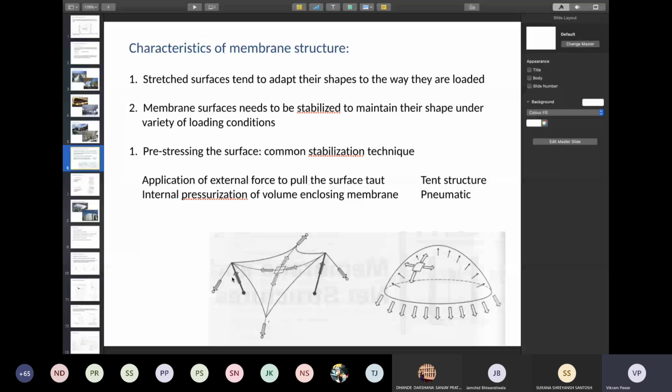Also, in this case, you have something called an anticlastic surface. One direction of the curvature is upwards, the other direction of curvature is downwards. With these two opposite kinds of curvatures, you are able to have a stable fabric over here. Whereas this structure is a synclastic surface. Now this obviously is not, because it is pulled at some corners.